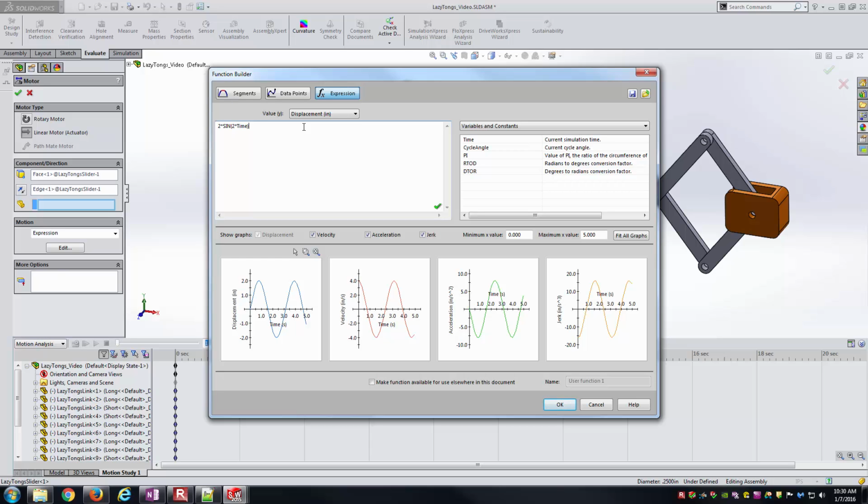One of the things you want to watch for is to make sure that this has a green check mark. I actually made a video prior to this and I forgot to do that, and it wouldn't run because it thought there was something off to the right. So be sure that after your last parenthesis, or last characters of your expression, there's nothing extraneous sitting out there that you can't really see. Here I just hit the delete key a few times, and it seems to make everything happy.